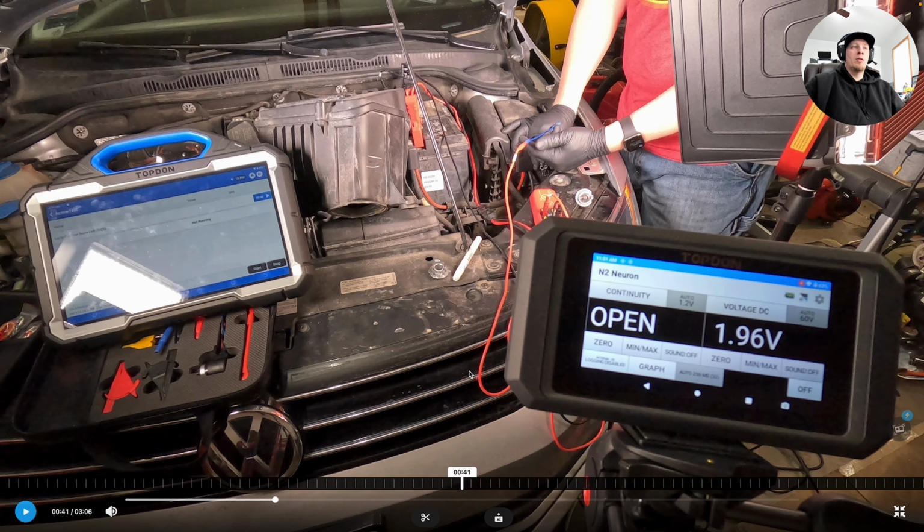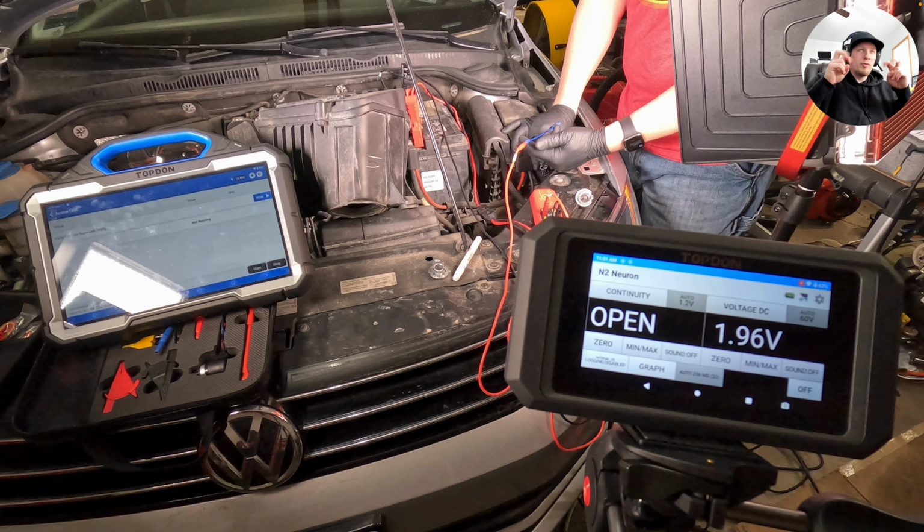At this point, it's pretty easy for us to determine that this is a test voltage, if you will, being sent out from the central electronics module. Generally speaking, modules will do something like this where they will send out a small level of voltage to check the circuit for integrity when the circuit is not powered up or active. They may monitor this. Some modules do this, some modules don't. Sometimes you will see this voltage, sometimes you will not.